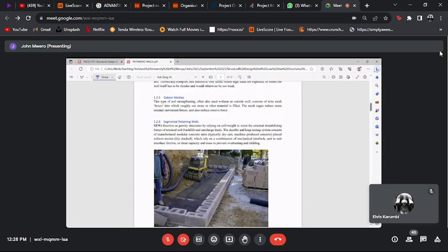Okay, they are all designs of retaining walls, but they have to be sloped. You cannot do gabions vertically like that. You got to step them. So you got gabions here. You've got another one overlapping there. So they are stepping like that. Again, they've got to be properly checked for design. If not, they have a tendency to fail quickly.